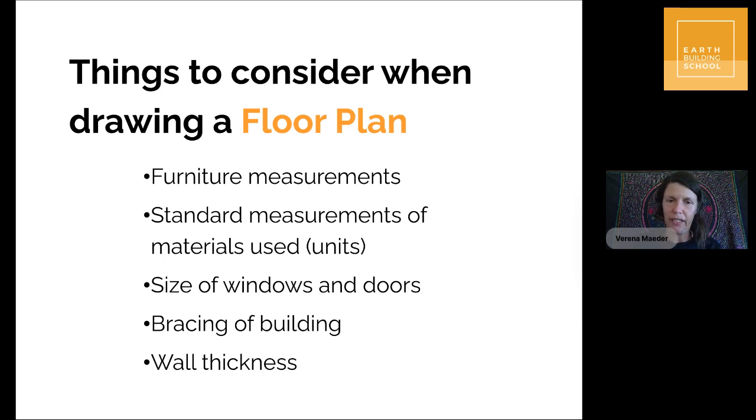And the other thing is the wall thickness. So when we're talking about 10 square meters, we're talking about interior measurements. So the actual usable floor space is 10 square meters, and your wall thickness is beyond that. And the wall thickness can be anything between, let's say, 100 millimeters for a timber frame, or 200 for a timber earth hybrid, to 280 or even more for your solid earth construction, or even maybe a straw bale construction where the walls are much thicker.